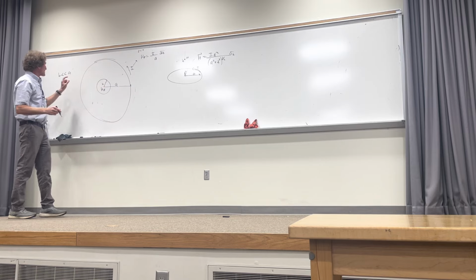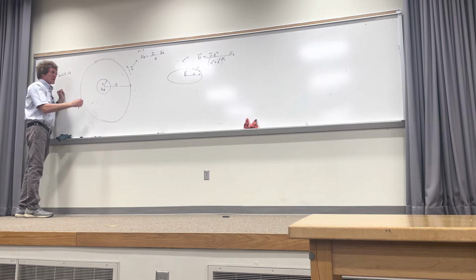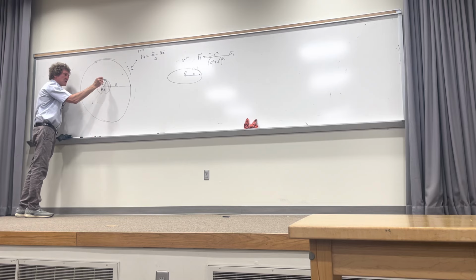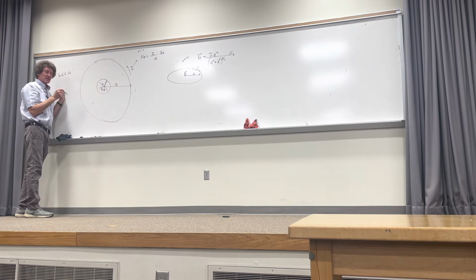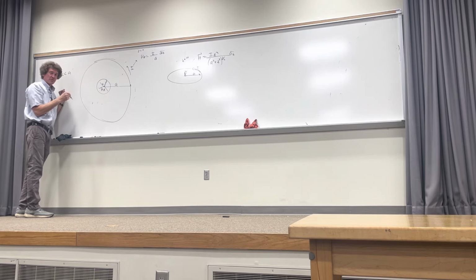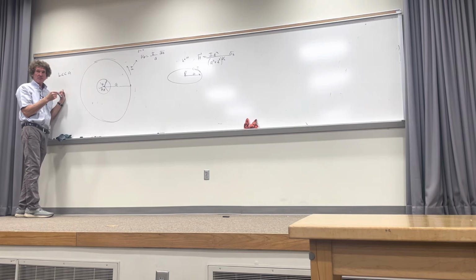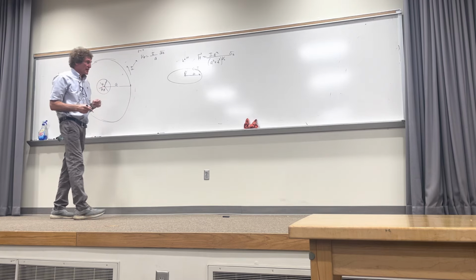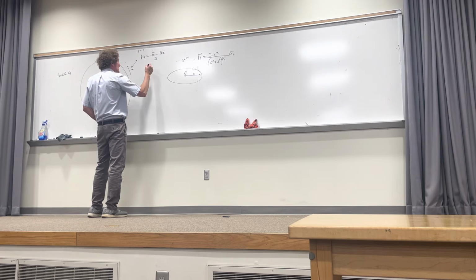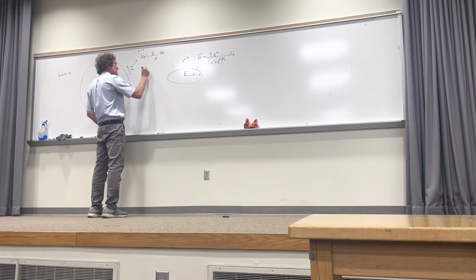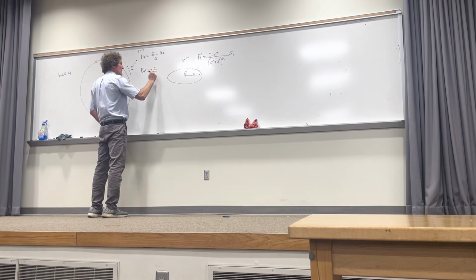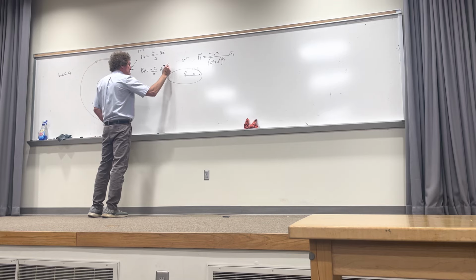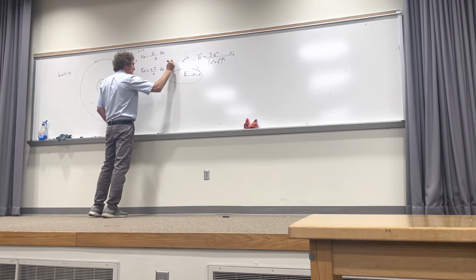Here's the reason I put this. If B is very small, then the amount of change in the H field over the surface of that inner loop of radius B is insignificant. Y'all follow me on that? We're assuming the H field doesn't change much because that B is so small. And so that H field will give us a B field, simply mu I over A, and this is for rho less than B.